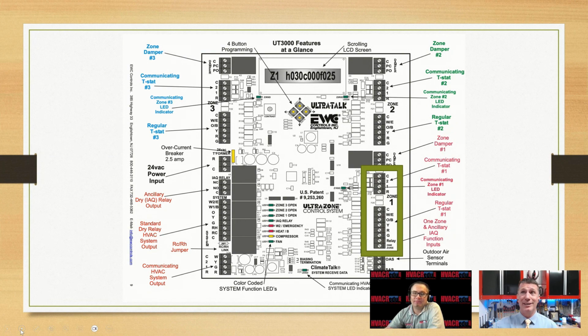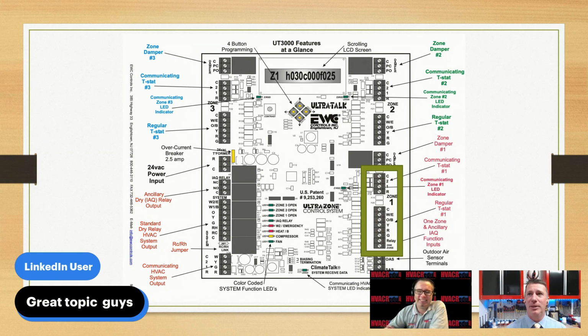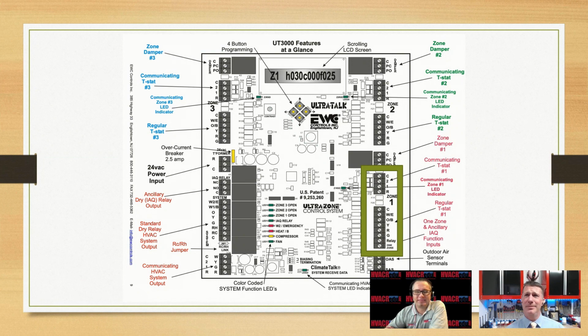I'm surprised that we don't have these for every other manufacturer. Part of that, talking to my friend that's the engineer for this board, is that the manufacturer just won't give us all of their data for the language they're speaking. Well, maybe one day, just like we have LonTalk versus Modbus, we'll have a Niagara system that can translate. A universal communication for unitary. Geez, wouldn't that be nice? Similar to our OBD2 terminal, like we are talking with cars. It just makes sense, wouldn't it? It would make so much sense if we could, as an industry, coerce our manufacturers to use a unified common platform so we have a controller. It just basically becomes an OBD system for our industry.